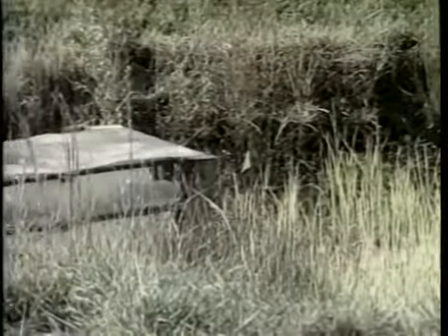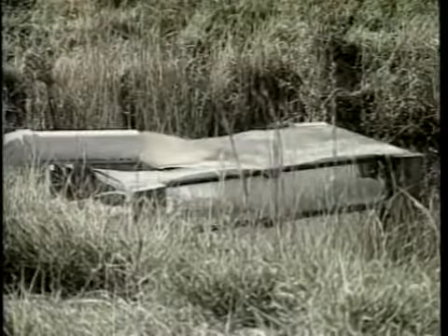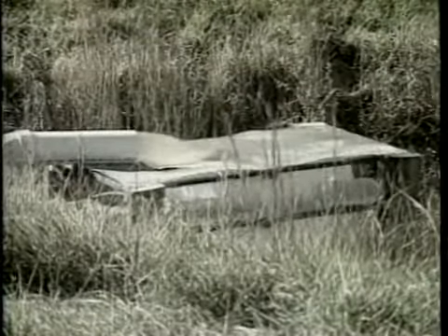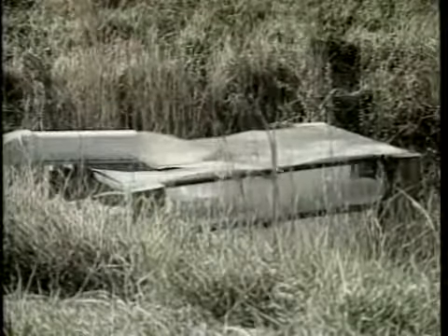Pumping water into the pond seldom helps raise oxygen levels unless the water is pumped over a splash device or sprayed out over the pond, thereby allowing oxygen to diffuse into the well water. This is because most well water is nearly devoid of dissolved oxygen.